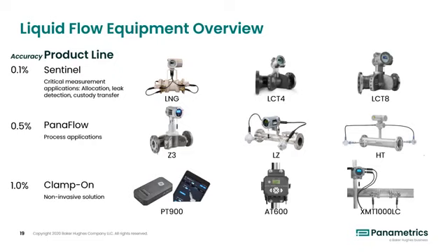All of the previous flow meters required a manufactured spool piece to be dropped into your line. If your process does not allow for the line to be brought down, or if you need a more temporary installation, you may elect to go with the clamp-on systems.